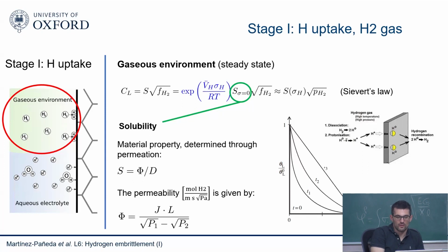I think there's a bit of noise related to electropermeation. We'll discuss that later. It's a complicated test. But the gaseous one also has its own issues. You can generate oxides. I think the main advantage of the gaseous system is that it allows you to go to very high temperatures, because diffusivity can change. I'll put some numbers there so you can see the difference between materials, but it can change quite significantly.